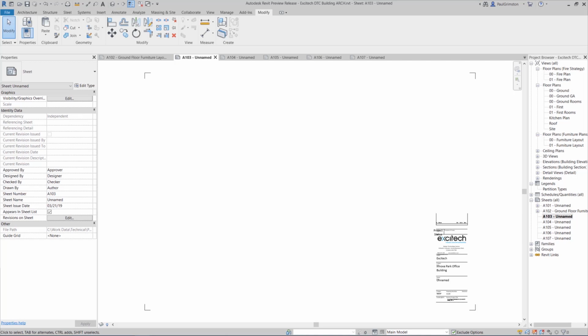The next feature we're going to have a look at in Revit 2020 is the ability to copy and paste legend views between different sheets and also back into the same place if we need to do that. In previous versions, to place a legend onto multiple sheets, we would have to place it on each sheet individually and then go and position it, which can be quite a time-consuming task, or we might need to resort to some kind of scripting or plugin to automate this for us.